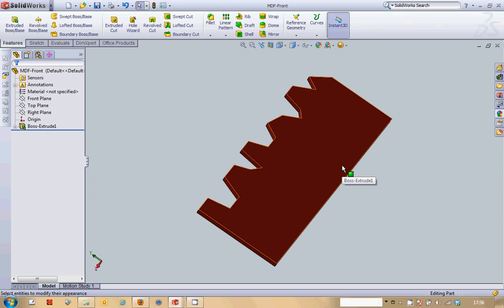Your middle component should be 150 millimeters wide, and it should be 90 millimeters tall before you start drawing that complex shape. And your back piece, the largest one, should be 150 millimeters wide again, and perhaps this time just 120 millimeters tall. So that will give you 3 heights, one that's 60, one that's 90, and then one that's 120.